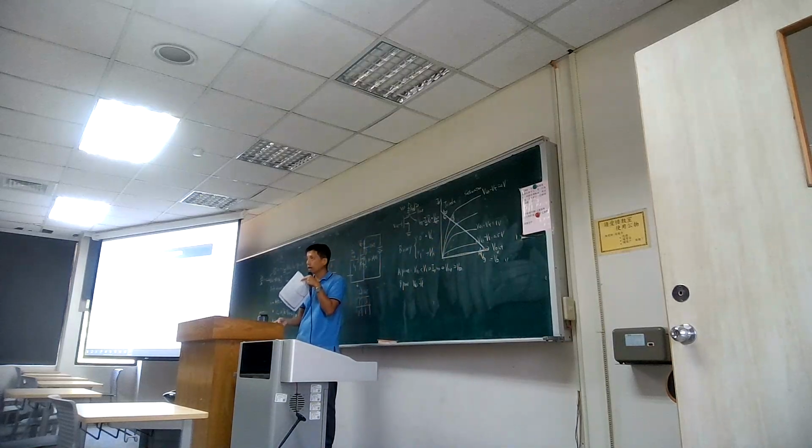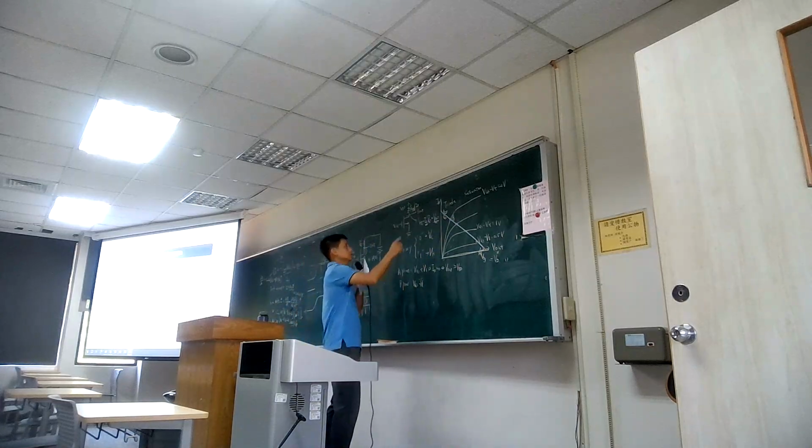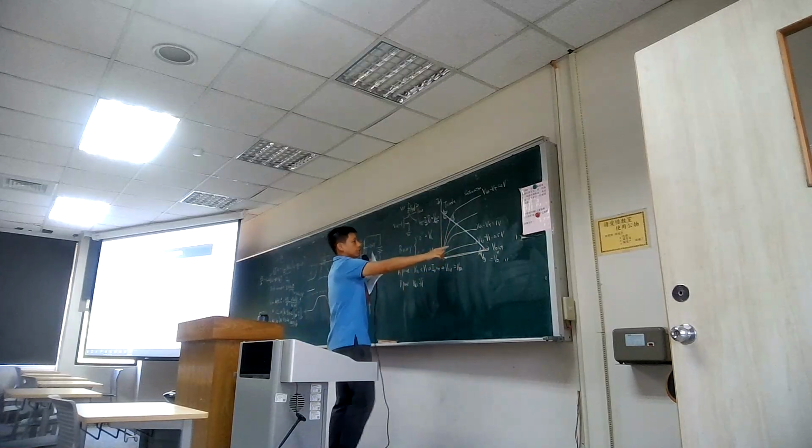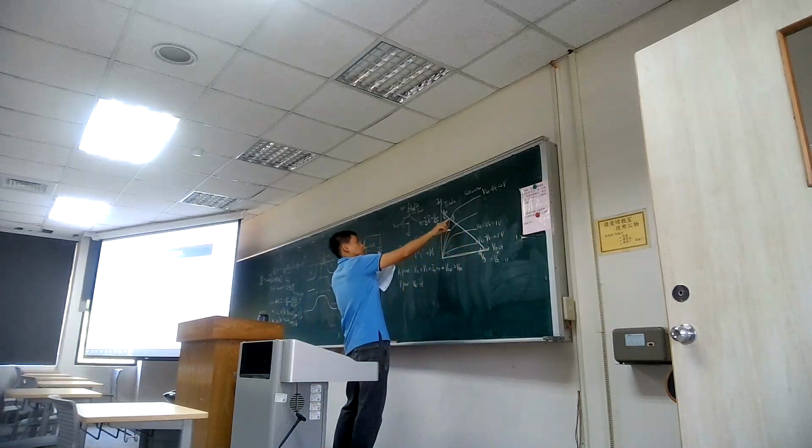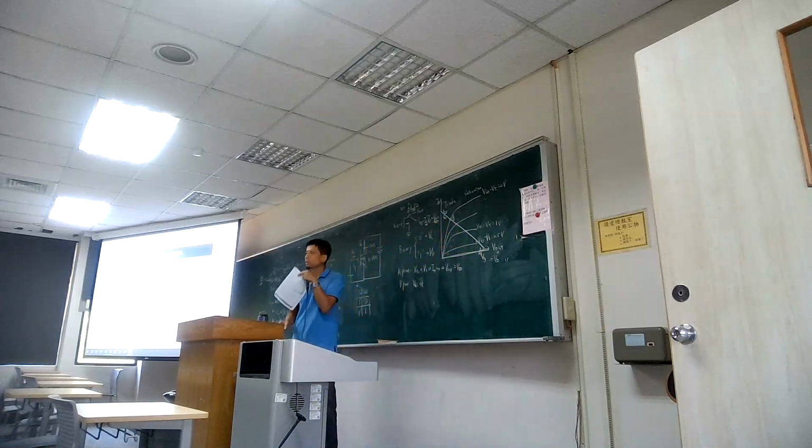But once you get the current flow, your VDS is also high at this moment. That means you get this VDS first as a high voltage. But later on, it will be dropping. So you first get VDS high, so you work in the saturation region. But later on, it will go back to the triode region.